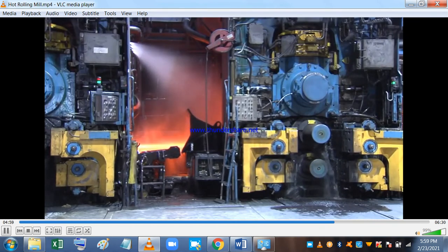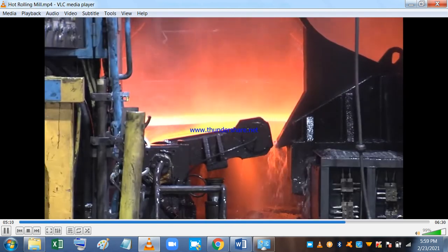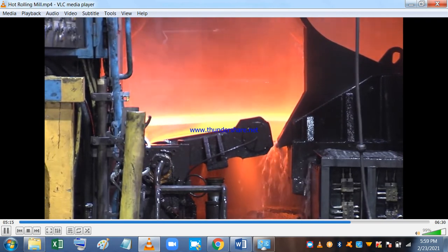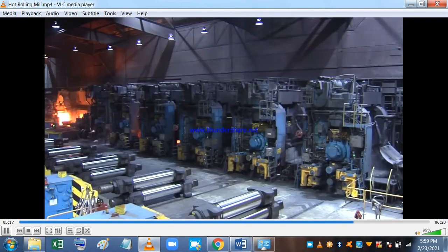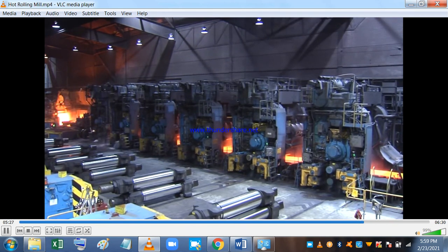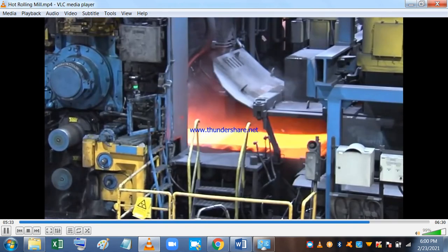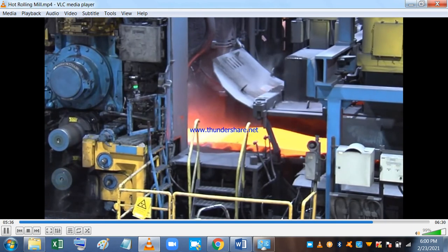Between the rolls we see an uplooper, which measures and controls, amongst other things, the line speed and the strip tension. The swinging motion that can be observed is when the uplooper is adjusting itself. This is an adjusting roll. In order to control the profile and the flatness of the strips, the working rolls are horizontally adjustable. The first stands control the profile, and in the later stands the flatness is controlled. It's very important to have a correct strip profile and flatness before any post-processing starts.